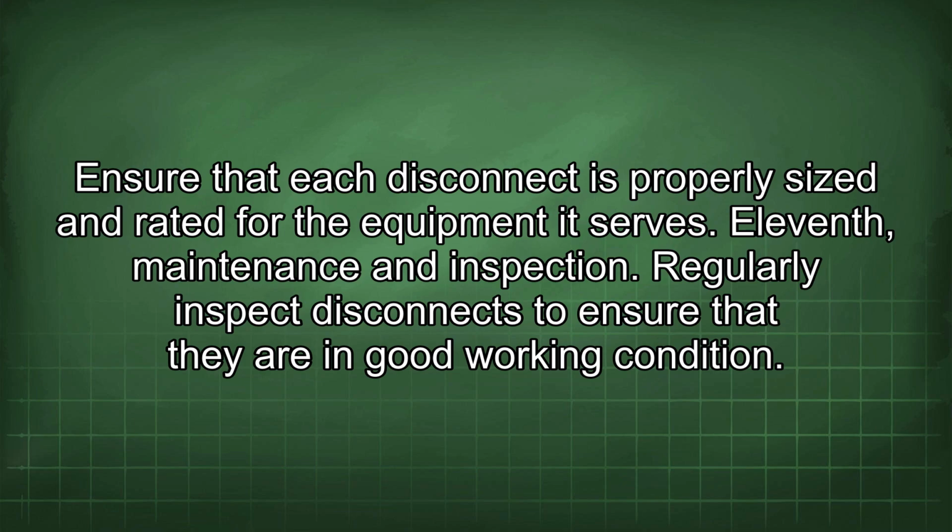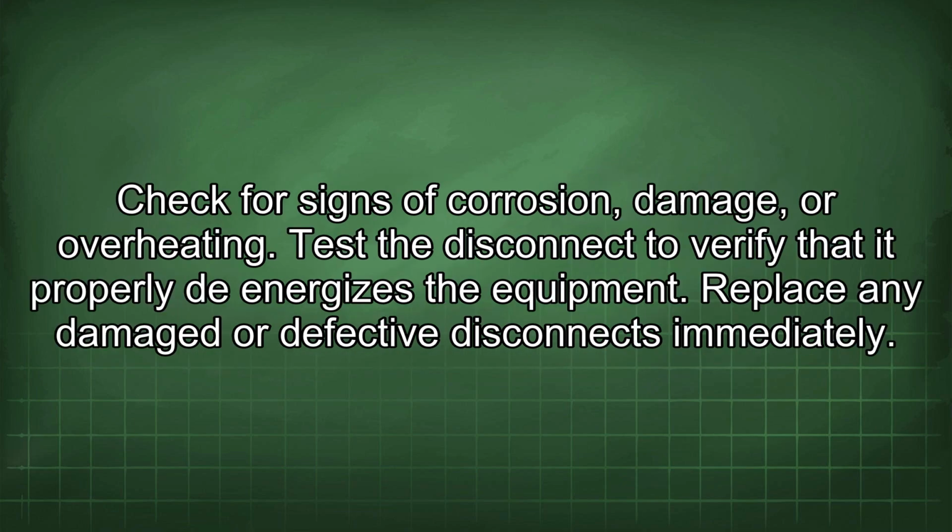11th, maintenance and inspection. Regularly inspect disconnects to ensure that they are in good working condition. Check for signs of corrosion, damage, or overheating. Test the disconnect to verify that it properly de-energizes the equipment. Replace any damaged or defective disconnects immediately.